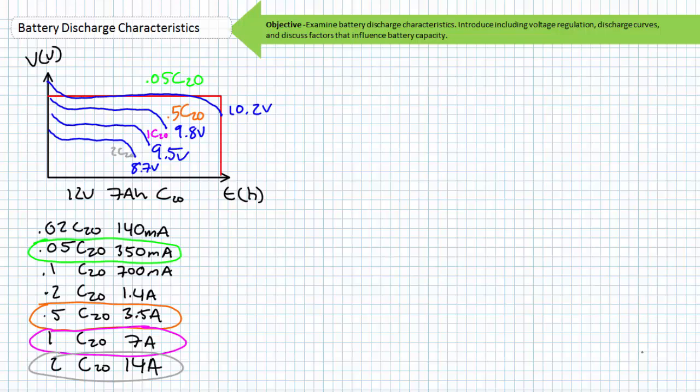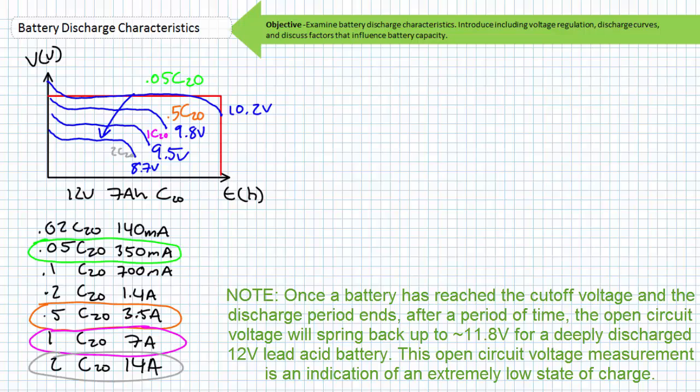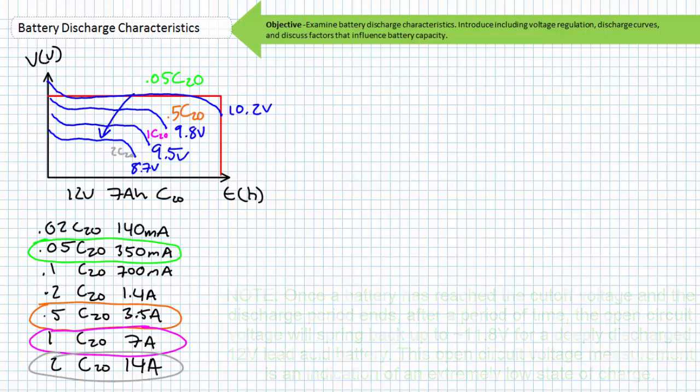What successive analysis yields is a collection of discharge curves for varying discharge rates. Each increased discharge rate yields reduced working voltage and possibly a different cutoff voltage. You'll notice the different manufacturer recommended cutoff voltages represent the downturn of the knee just before it rolls off the cliff. This ensures a reasonable quantity of energy is extracted from the battery, yet the battery isn't placed at risk of being permanently damaged.